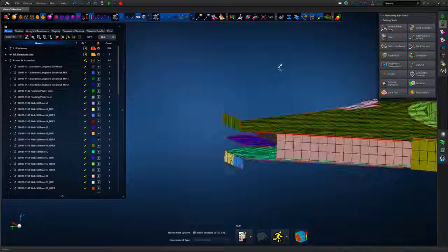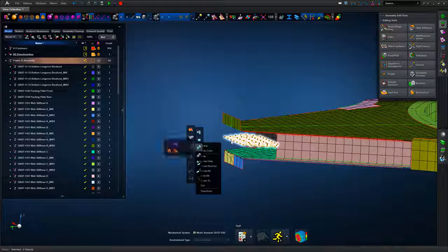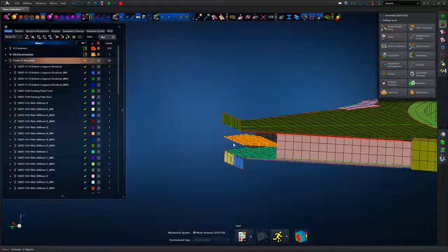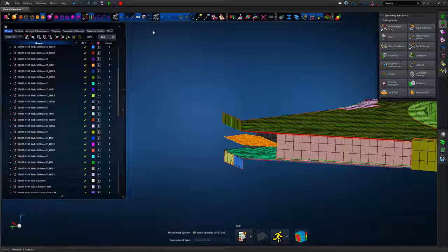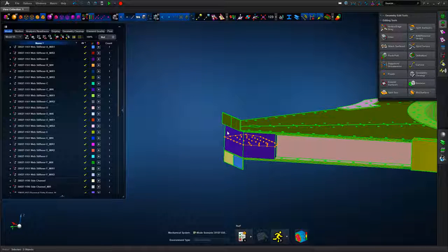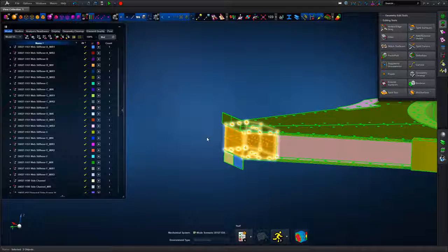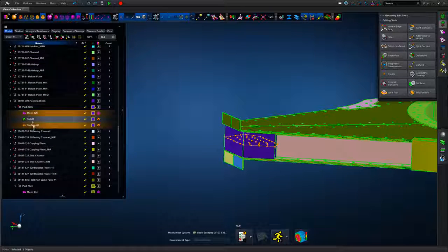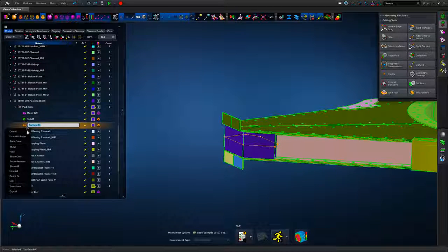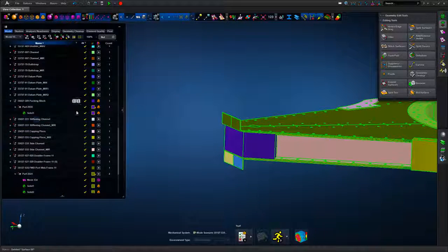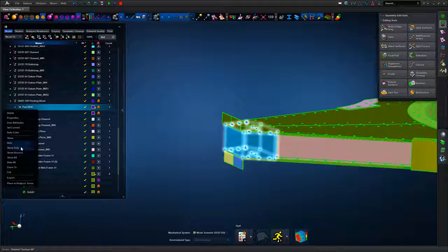rest of the shells. Looking at that in detail, we can see the mid-surfacing operation has mid-surfaced basically a thick solid, which doesn't lend itself well to the shell definition. We could probably get away with it from an analysis perspective, but wouldn't get very good results for stiffness definition or even connection definition at that interface.